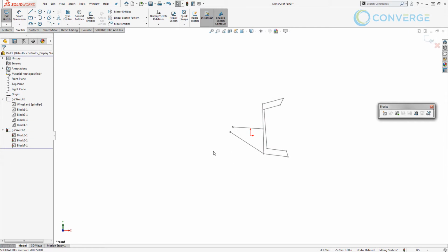So this functionality, by taking your mechanical designs down to 2D, using sketch blocks and creating that mechanical motion, can help save you a lot of time from designing parts in 3D before you really know the layout and the geometry of what you're designing. Especially when it comes to planning out 4-bar or multi-bar linkage systems, even if they include gears or belts and pulleys to drive them, having this basic representation of that mechanical motion can save you guys a ton of time.